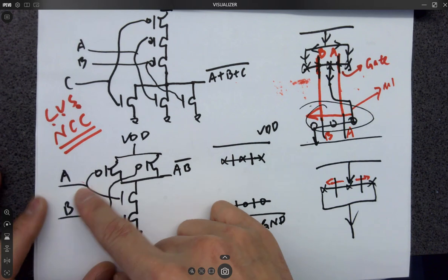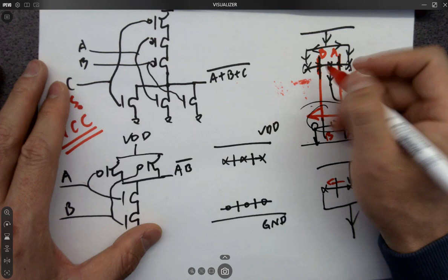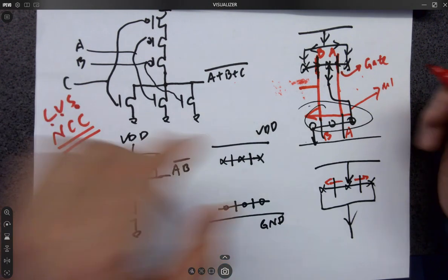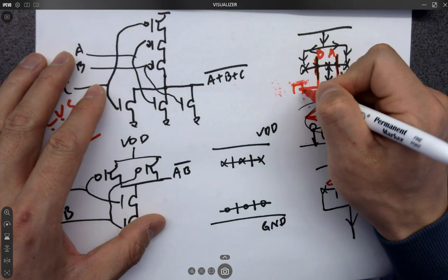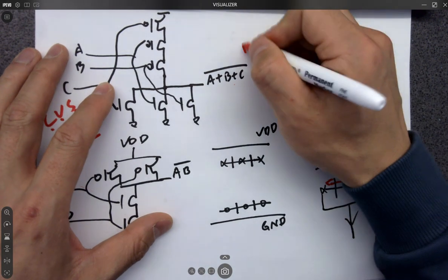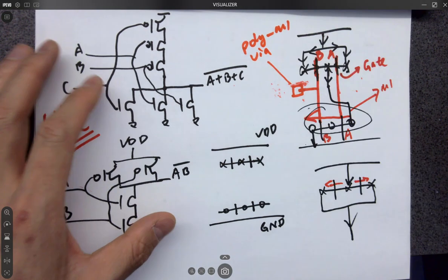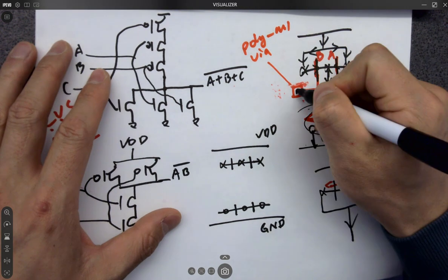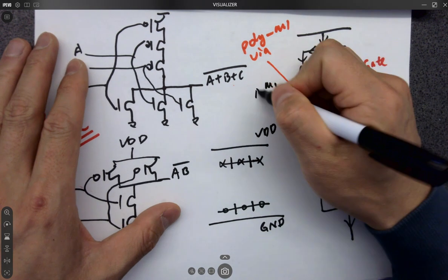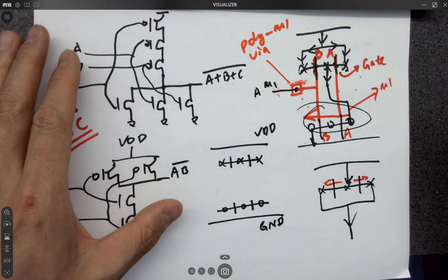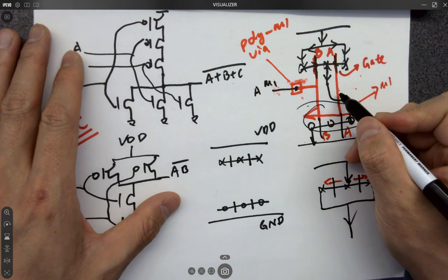And you need the metals for the gates, right? So that all the signal lines are shorted to metals. So in that case, you need a little poly extended to the outside of the gate area, and you have a little node which is poly to metal 1 via. Okay, and then you got a little via here in the middle, so you can connect to metal 1. And there's a little port A here. What about this guy though?